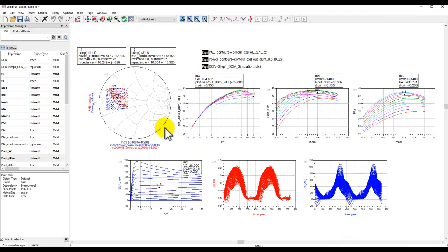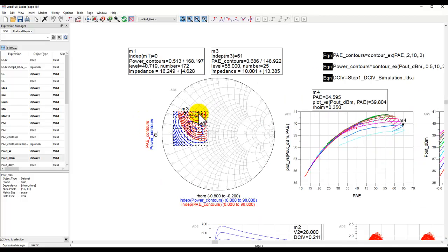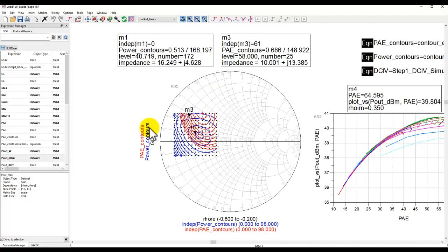The second way of looking at it, in case you do not have that information in the data sheet: remember, the power devices which we are using, such as LDMOS, gallium nitride, and so on, usually will always have low impedance. So the region which you would like to check in a Smith chart would be around this area. If you divide this circle into quadrants, usually it's the second quadrant area or the third quadrant area. That's where mostly you will find the most optimum conditions for your bias, for your load in the transistor. So you can always start with these two zones.